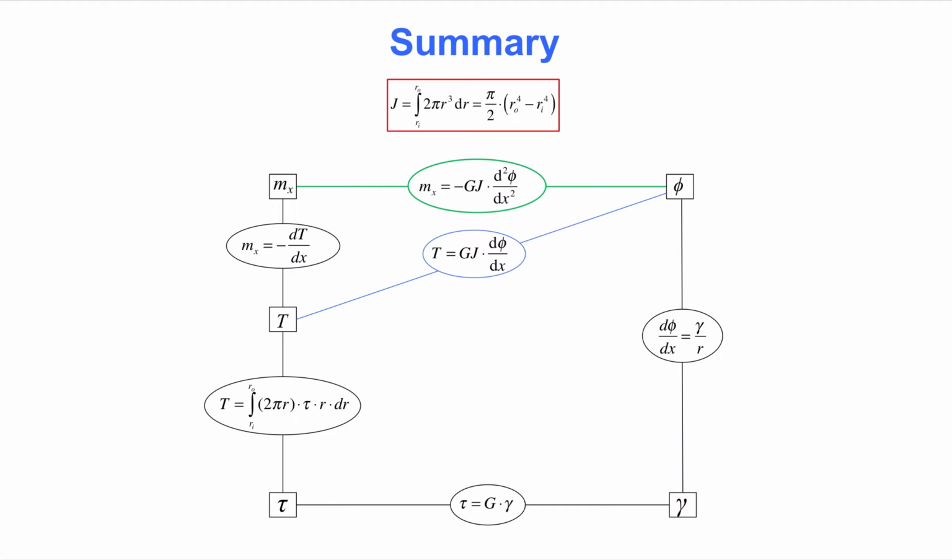This form of this boundary value problem is somewhat similar to that for truss members. The equation in the blue circle indicates that the rotation along a beam member that has a torque applied at one end varies linearly, just like the longitudinal displacement of a truss member subjected to an axial force at the end also varies linearly. In fact, the general solution to this differential equation is as simple as that in the video on truss members, so it is omitted in this video.